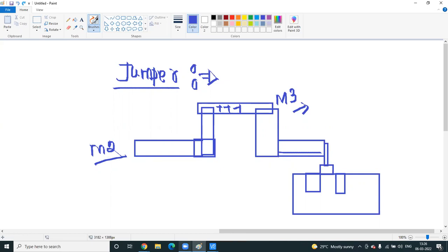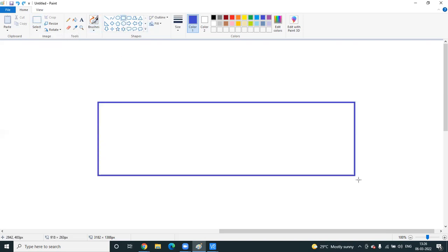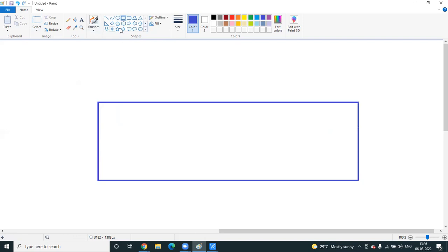Gururaj, you got the point? Yes, sir. Yeah, so this is the step by step. First, you have to reduce the antenna ratio manually, the metal area by gate area. If it is not possible, use a jumper. If a jumper is not possible, the third process is called antenna diode. This antenna diode I already did.